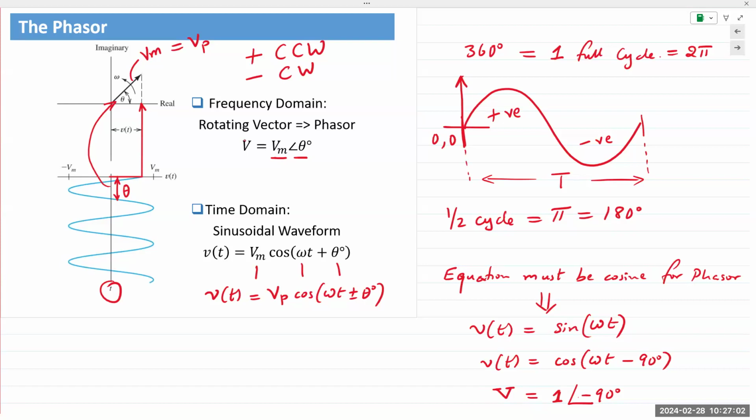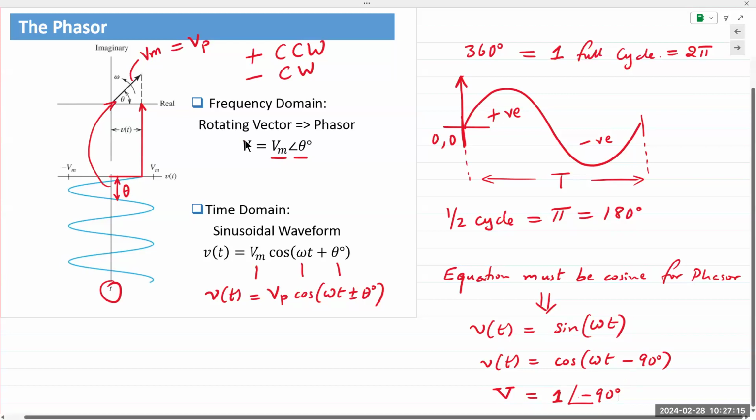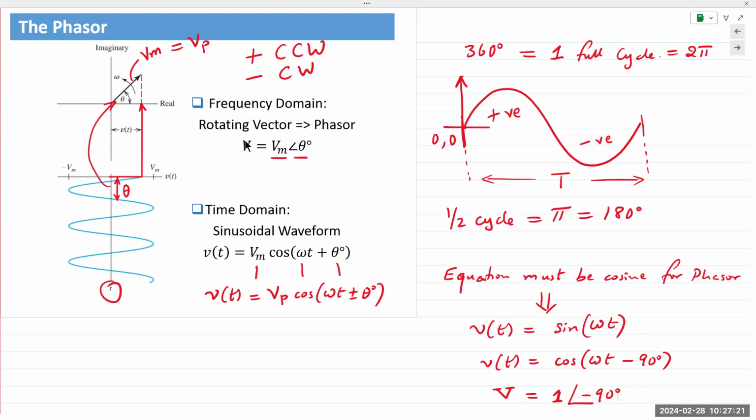No, we don't need to. We keep it separate for this specific reason because we need to perform a phasor transform. So you're talking about this one? Yeah, it's a phasor. The phasor does not include any frequency information. There's no omega in there in the description. Again, remember, it's a vector. A vector needs only magnitude and phase angle. That's it.